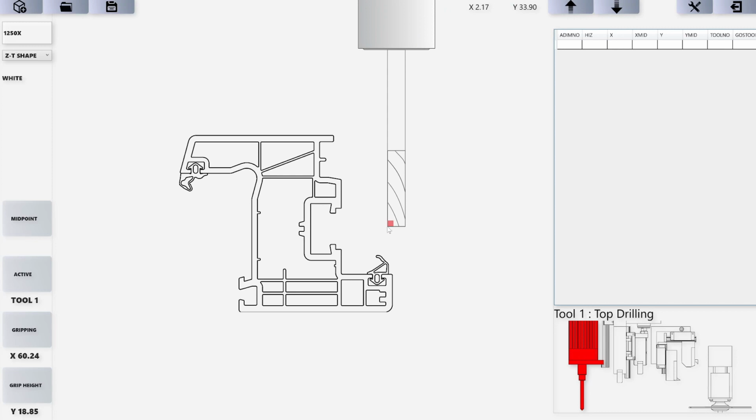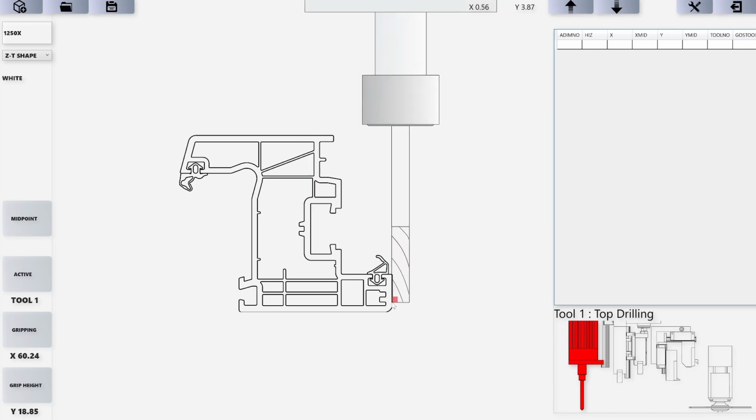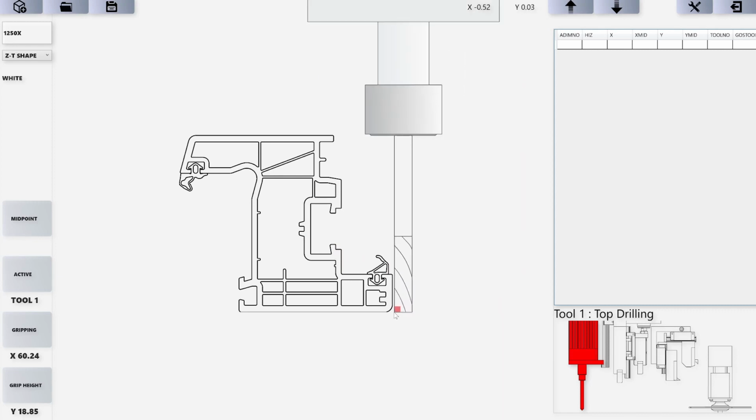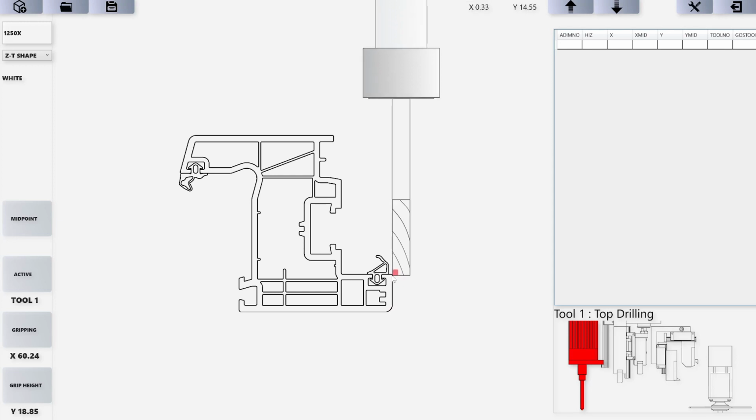And the mouse cursor is aligned with exactly the 0 position of the tool. And there's a red rectangle. This rectangle shows that the left bottom corner is my reference point for this tool. So in this software, we will be touching the profile with the mouse, but the machine also needs to know a reference point so it can calculate the correct coordinates.